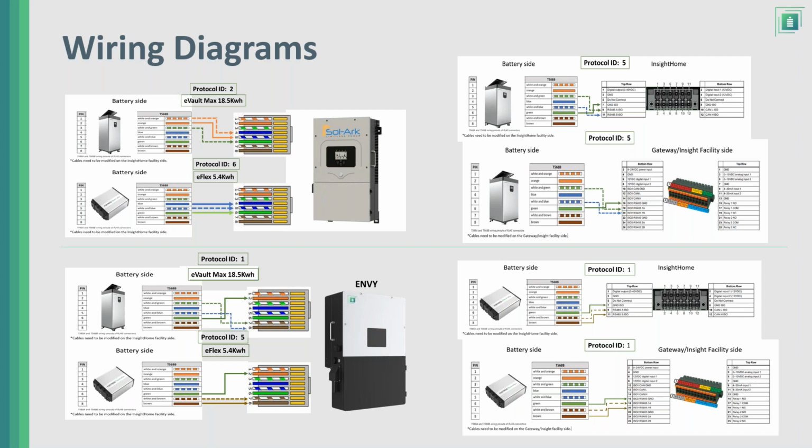It will have to go first into the inside home or inside facility. And you see the combination of pins that will have to be used, and to which pins on the inside side those pins will have to be provided. There's a whole procedure, once the connection is done between the batteries and the inverters, in terms of configuration that has to occur within the inverter. That's all documented in our inverter guides available on our website.